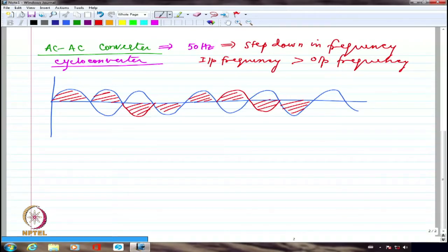Right? I cannot do this with diodes. I hope you understand, because diodes will conduct no matter what if they are forward biased. So I can't even have a dual converter with diodes. I hope you understand. I can't connect back to back. It is going to essentially burn completely, because one will have plus on the top and minus at the bottom. The other one will have minus at the, again the other way around. So you will try to connect the 2 plus and minus.